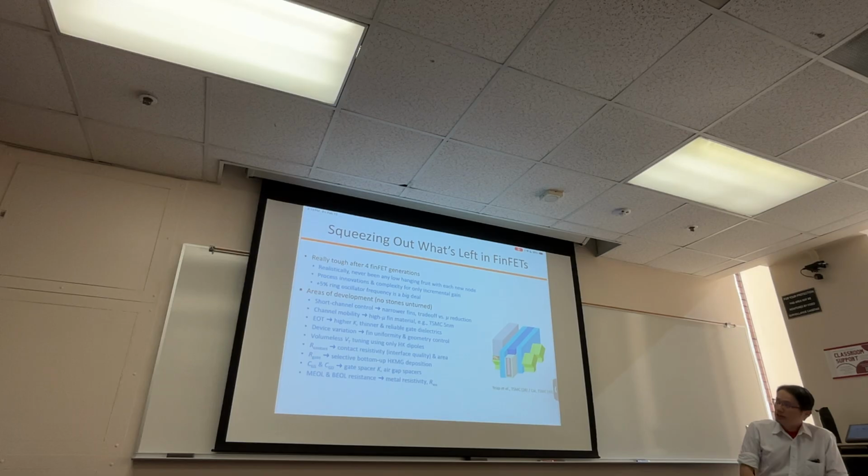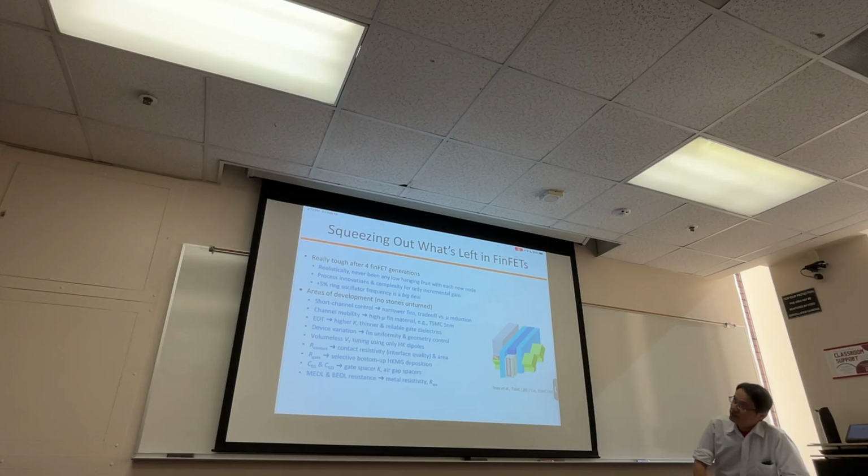So at a certain point, when people move to 16 or 14 nanometers, that's where the first generation of FinFET, right? And then people still go through different iterations. So 16 to 12 to 7, right? To 5 nanometers. People still were able to keep squeezing what they have through the FinFET. But realistically, we run out of the margin. Okay, those process engineers, not us, not you. Okay, it's the process engineers. They pretty much run out of the limit that they can achieve from the FinFET, right?